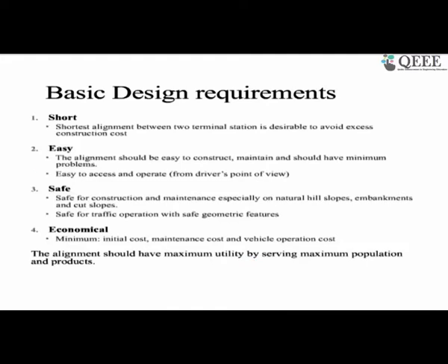Okay, now I think I received another question, or the same question: how are conflict points evaluated in national highways and expressways? I answered this last time as well. The conflict points are evaluated the way they are evaluated at any other location. There are primarily three types of conflict: crossing conflict, merging conflict, and diverging conflict. And based on that, we need to look into it.